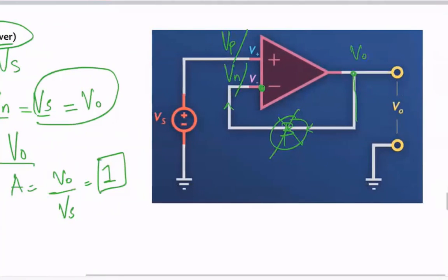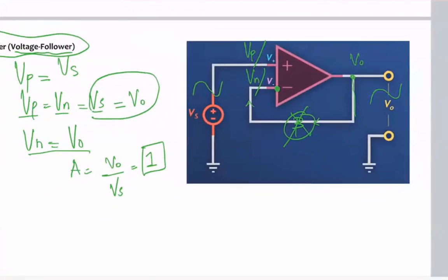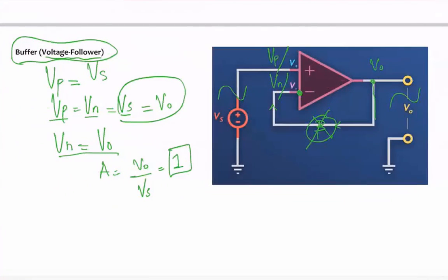But what is the point of using this operational amplifier in this configuration, when I am supplying something like this, and also at the output getting the same thing? There's no amplification. Why are we doing this? Now you would know, it's doing the voltage follower, because whatever the voltage is, say it is 6 volt over here, you get 6 volt over here, correct? Because VP and VN need to be the same, that's why it's referred to as a voltage follower. Whatever the voltage is here, it'll just keep it constant. It won't change.